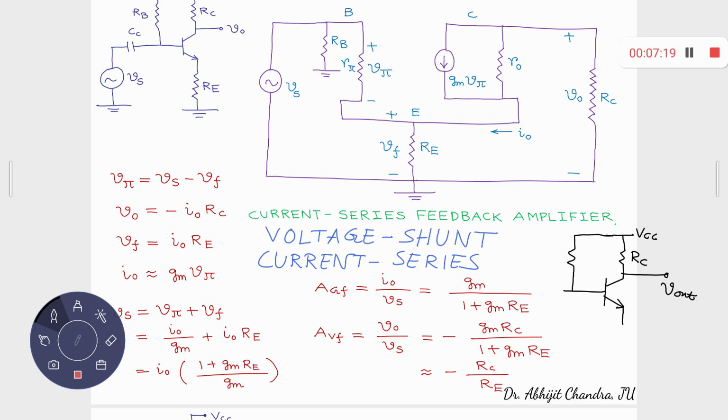So I have to connect this output voltage, I have to gather this output voltage so that it becomes a voltage kind of sampling. How to mix? It's a voltage series. Series mixing means what? You have already observed this for current series kind of feedback. Whenever you consider series mixing, you should have a resistance present there and you connect like that.